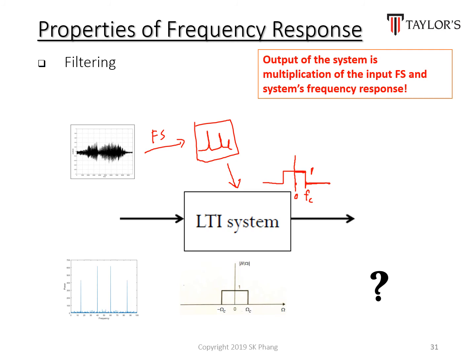So when you have the signals that pass through such a system, you can imagine that the signal that passes through the system is multiplicative. So these two signals and system will multiply together to obtain the output. So in the end, your output will be all the low frequency signals that is in front here, denoted by the blue color pointer. These are the low frequency signals. Let's say Fc is here. Anything before Fc is multiplied by 1.